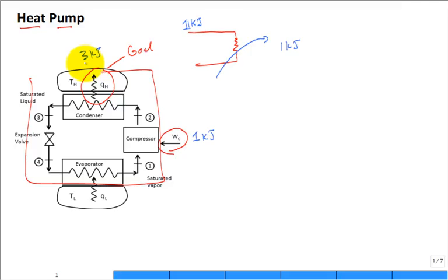So how does this work? Well, it's just the air conditioning system run backwards. And actually, a lot of them will just have valving, and they'll have the same evaporator and same condenser running, and they'll just change a little bit, okay? So that they'll actually switch what is happening: the condenser will become the evaporator, and the evaporator will become the condenser, okay?